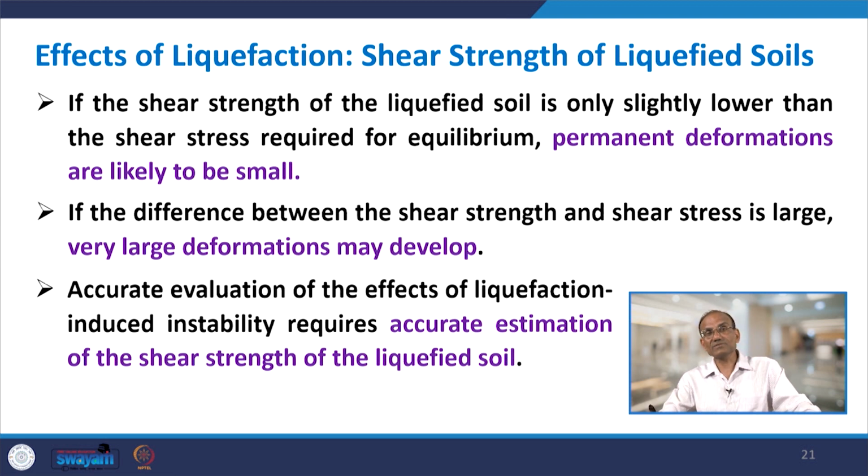Continue with the shear strength of liquefied soils. If the shear strength of the liquefied soil is only slightly lower than the shear stress which is required for equilibrium, permanent deformations are likely to be small. So, if the difference is not large between shear strength and shear stresses, then the development of permanent deformation will be less. If the difference between the shear stress and the shear strength is very large, then one can expect that very large deformation may develop. Accurate evaluation of the effects of liquefaction induced instability requires accurate estimation of the shear strength of the liquefied soils.